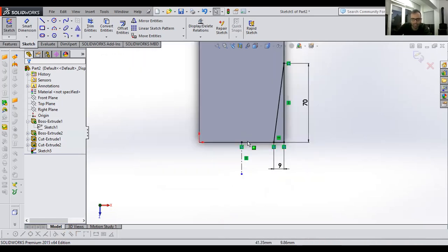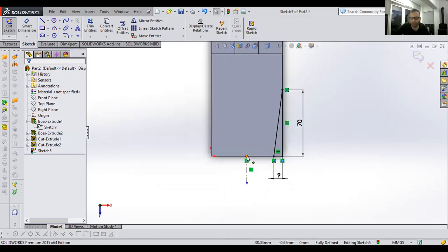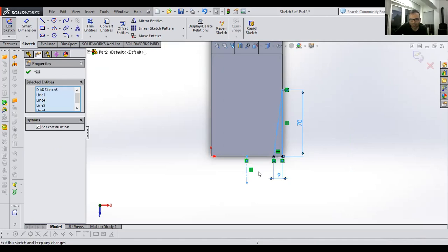Now what I did, I tried to make a center line here. Now I'm going to select whatever I did in this sketch. How is it possible to select? I can click on a point outside of the sketch and try to make a rectangle. But be careful, the sketch rectangle is not activated. Look, if you select this one, everything will be selected. The color of the lines will be blue, it means that it is selected. This is the possible way.